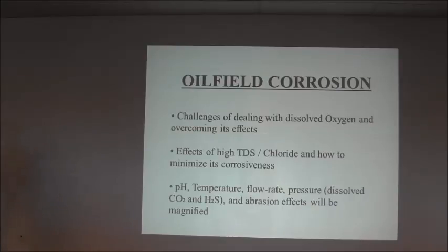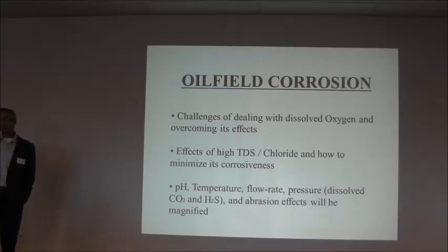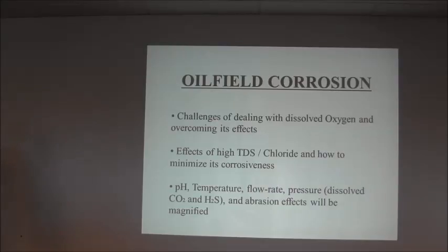Again, as the industry keeps going towards more water recycle and water reuse, the handling of those high salinity fluids is going to become increasingly common. There's going to be more water processed through equipment, and that high salinity water is going to be pumped down. It's going to get oxygenated inevitably when it comes to the surface, and it's going to be pumped back down hole, whether it be in another stimulation or water flood or whatnot. So I'm going to really focus on those two things, dissolved oxygen and high TDS.